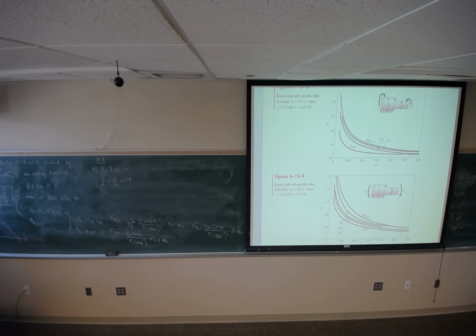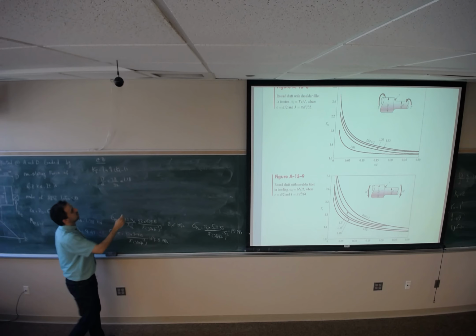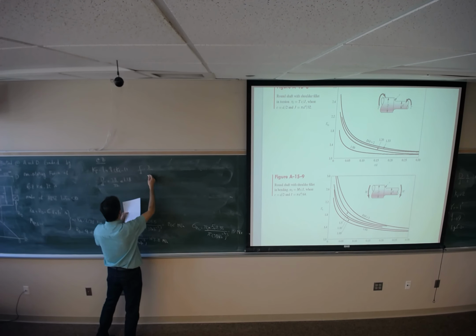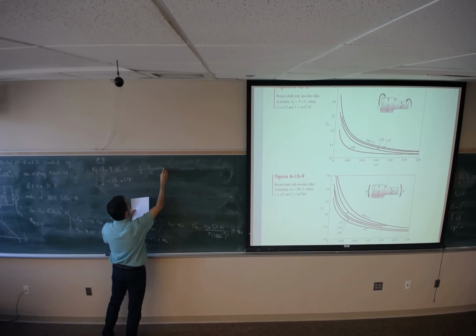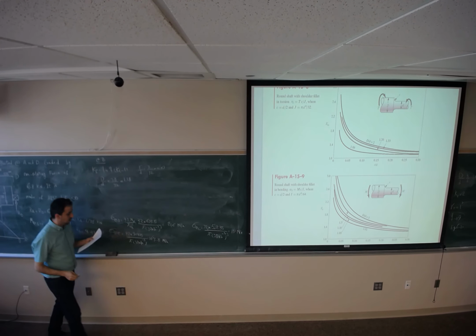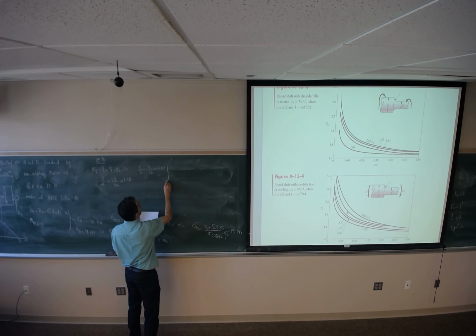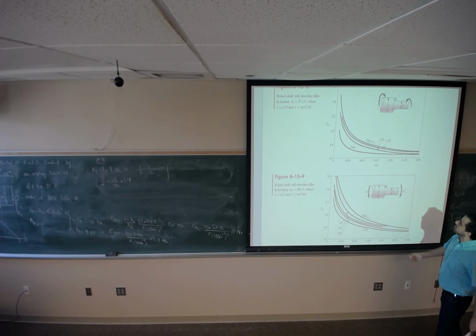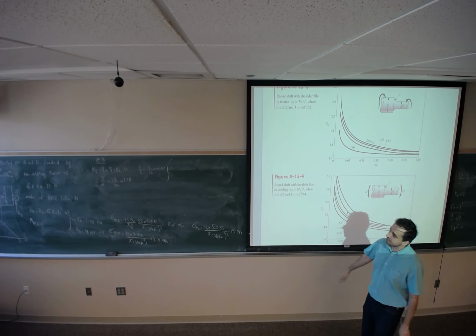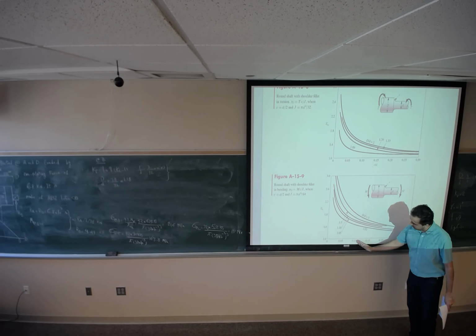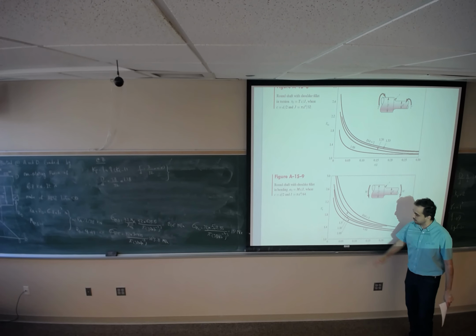The radius of the fillet is given as 3 millimeters. r divided by d is 3 divided by 32, which is 0.09. So r over d is 0.09, just slightly before 0.1.